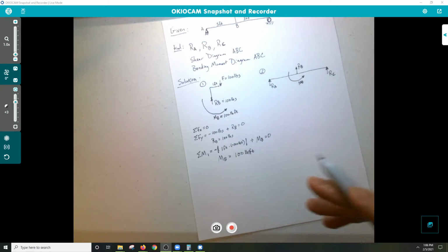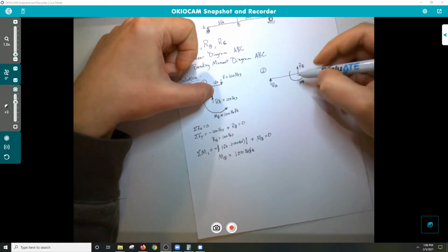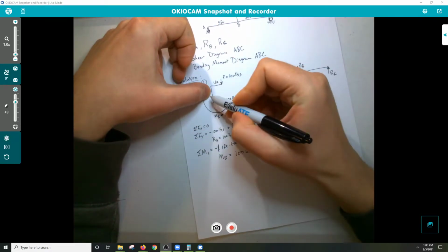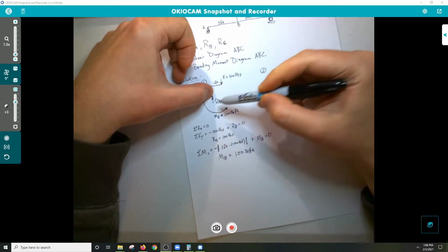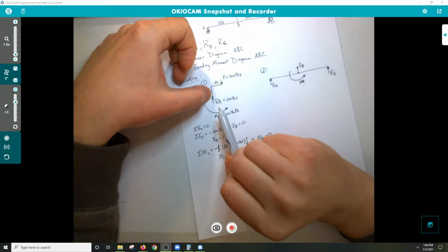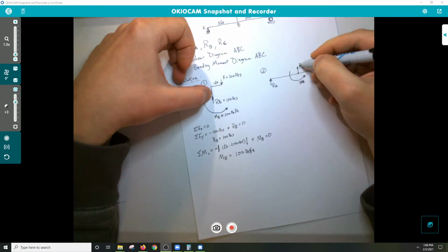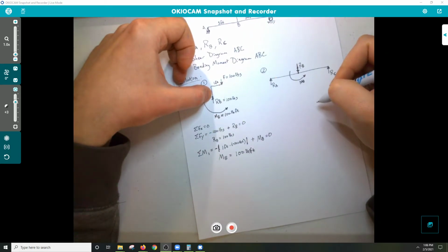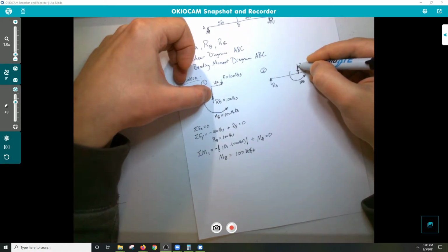And if you remember, when you break up free body diagrams at the same point, so our point B here and our point B here, we're going to get equal but opposite reaction forces as, say, we go from one free body diagram to the next. So since we know we have a positive 100 pounds here, we're actually going to have a negative reaction for B there. So we'll actually have that be 100 pounds downward. So that changes direction.